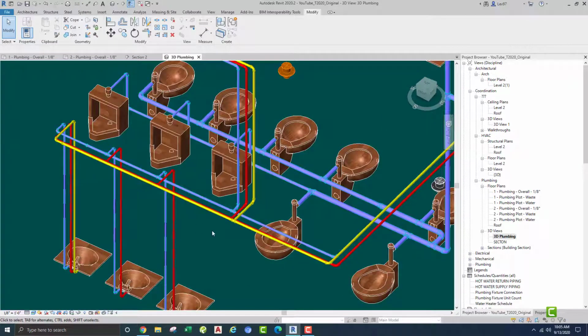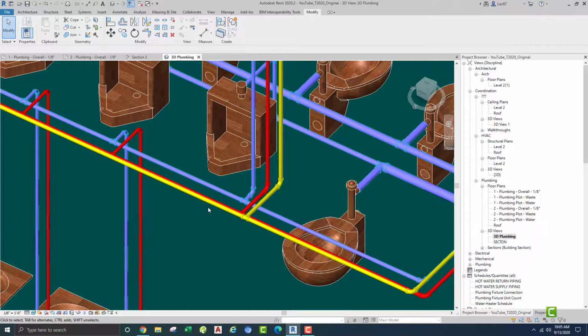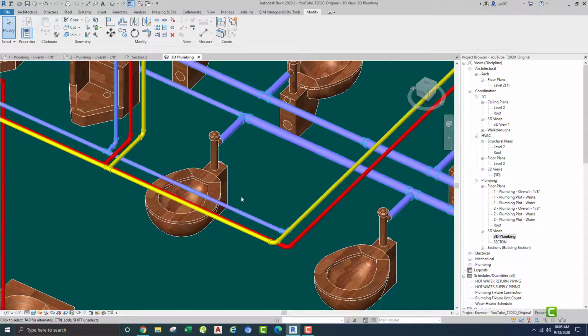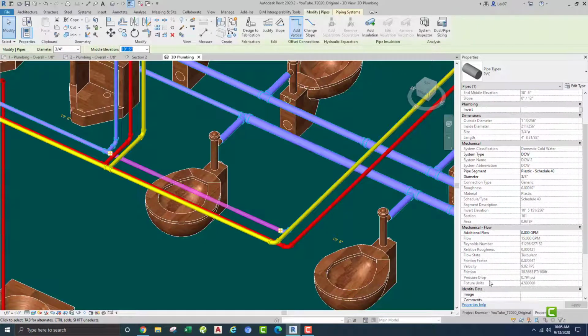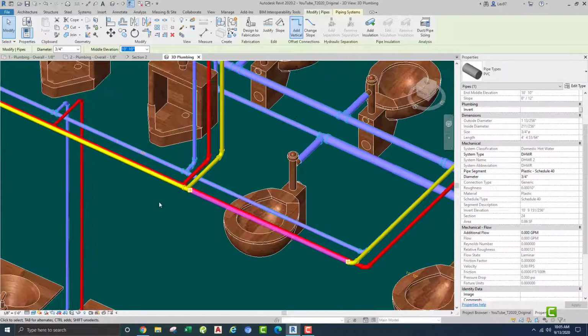to make sure the fixture units are being counted. So let's just, any random, let's make sure the circuit's not broken, because if it is, it's going to say 0 somewhere, right? Okay, so everything's being counted. Fixture units 4.5. Fixture units, I just need a number. So that's the hot water return.